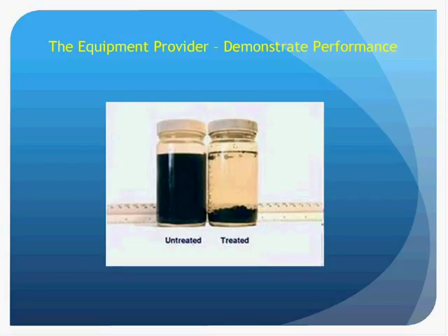A clarifier is designed to concentrate contaminants and have them settle to the bottom of a tank. This slide displays the general concept. The clarifier's efficiency to remove contaminants that are suspended in solution depends in part on the chemistry and the system hydraulics. As you see before you, there are 2, let's call them jars. The first jar contains untreated or unpurified material. The jar on the right contains the treated or purified material. Purified in the sense that the contaminants have been reduced in volume and have settled to the bottom of the jar. Next slide, please.